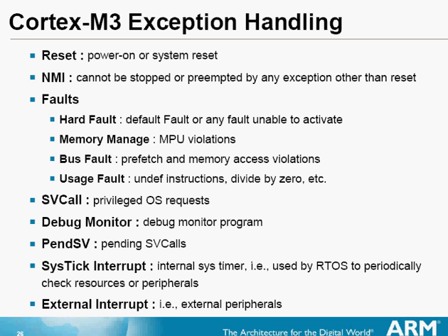First, reset, invoked on power on and reset. Non-maskable interrupt, NMI, an external interrupt activated by external pin that is unstoppable except by reset.